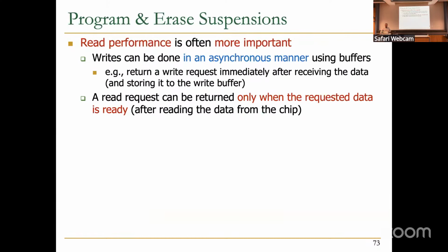Another important optimization is program and erase suspensions. So read performance is often more important because reads are usually on the critical path of the processor. And writes can be done in an asynchronous manner using buffers. So we write to the buffer and then we inform the host that we are done with the write, and we can do that write operation asynchronously in the background.